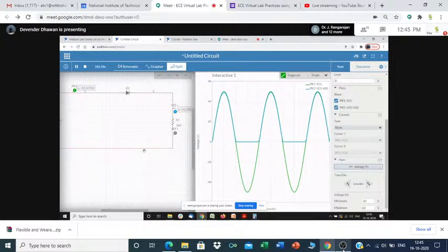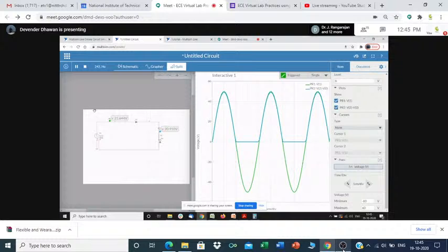So I don't need a transformer, but in labs generally we ask students to put in a transformer also in between, na? Because we basically are working on 220 volts, and we use a step down to convert it into maybe a 9 or 30 volt AC. Then we use this circuit in forward to clip the negative wave and try to convert it into a DC. Okay, so anyway, I just showed it in that.